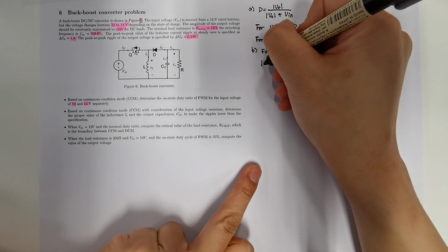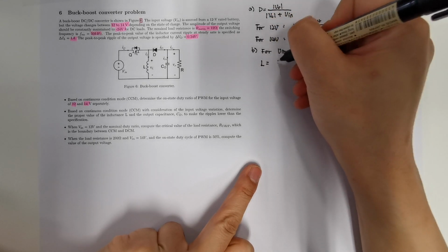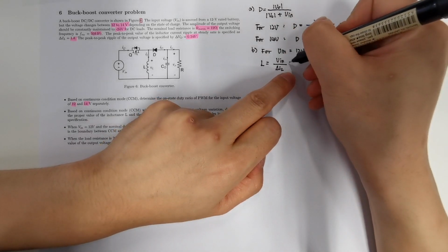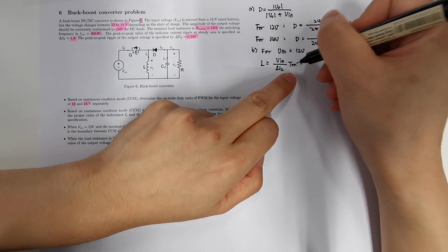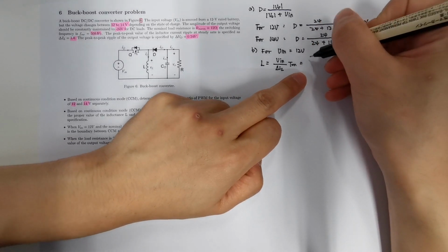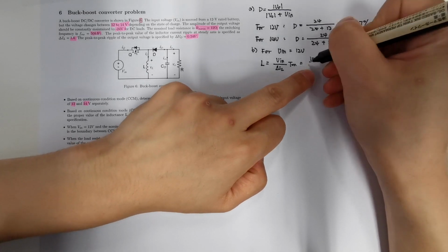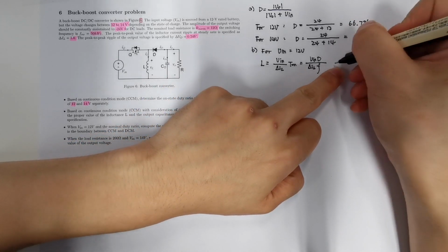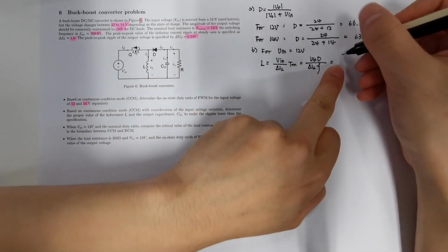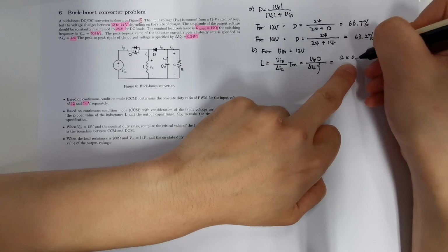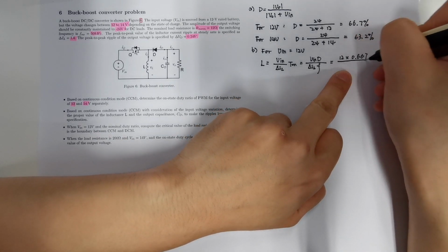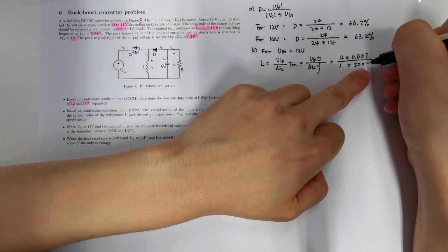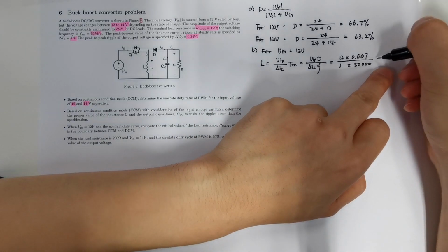We have our inductor as V in divided by delta IL times T on, and we can replace this T on with duty and frequency, which is V in times D divided by delta IL times frequency, and we now have 12 times 0.667 divided by 1 amp times 50 kilohertz. We got